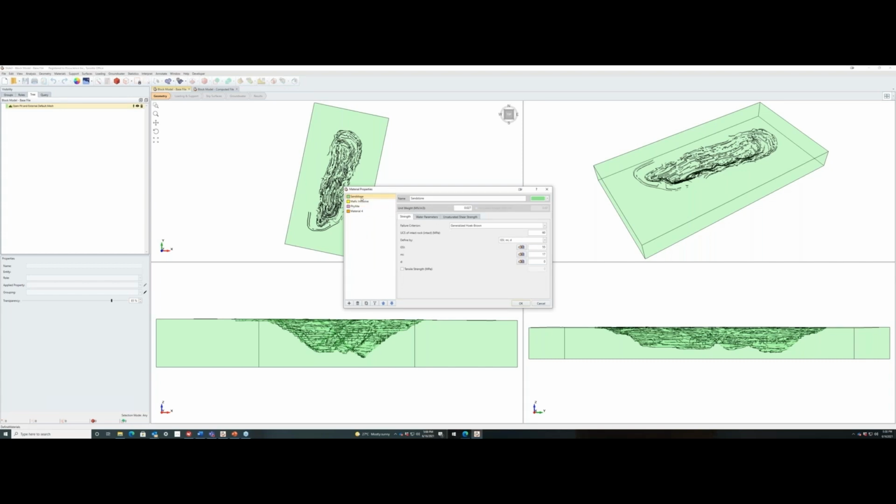And then what I have done is I told you the different types of rock masses we'll have in this model. There is a sandstone, there is a mafic intrusive, and there is a phyllite. And I've already defined their properties in this model. Now I am going to bring in the block model that contains information on which blocks have which of these materials within the blocks. So to do so, I'll first select material number 4. It's a default parameter material. We haven't done anything with it. So I select it. If it wasn't here, I could have added it from this dialog.